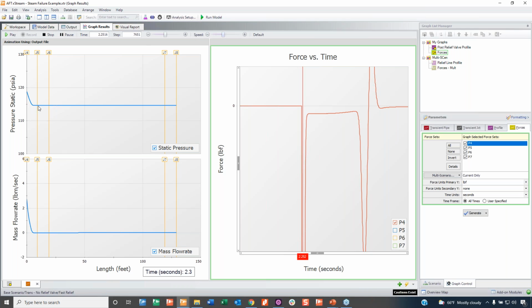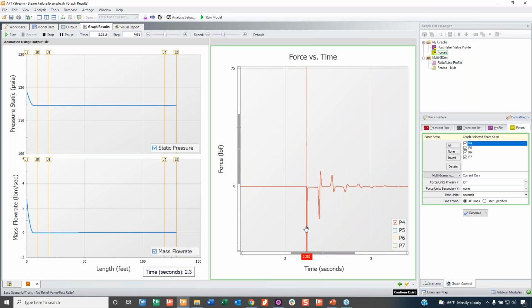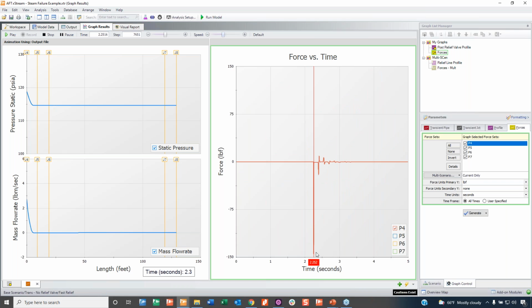the end of the pipe hasn't seen it yet. Again, we are on the order of magnitude milliseconds. So there's truly an imbalance, and a pretty significant one, even though it's only maybe a 5-pound pressure rise. The force resulting from that can be pretty major. I mean, everything's relative, so maybe 150 isn't that major to you, but it is major relatively to other cases.